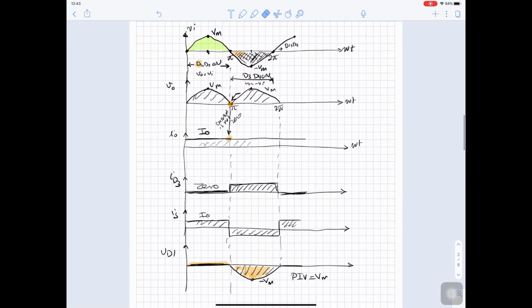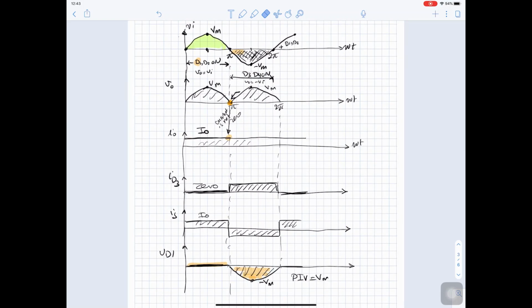So if you see any positive part here in your graph for V diode, you made a mistake. And these will be the waveforms. Now, if the inductance was just high, not infinite, not highly inductive, you should sketch I out to be something like this. So in this case, if L is not infinite, the current will increase, then decrease, then increase again.